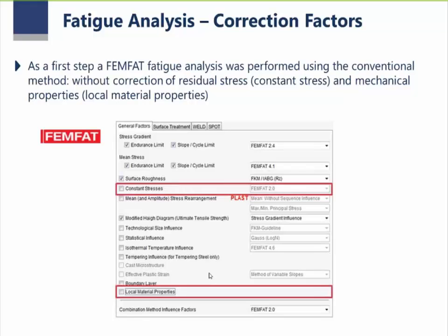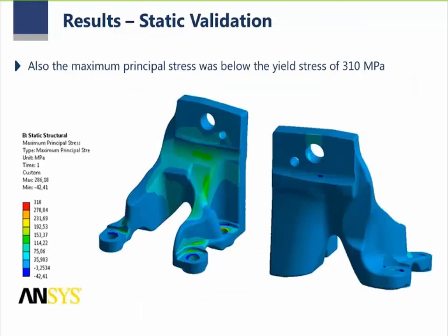In the standard procedure, when you have a simulation, you consider that every element of your model has a standard value of tensile strength, and also a standard value of the fatigue endurance. But when we get these properties from the MAGMA simulation, you see that there is some variation from part to part. So in this presentation, I will not go very deep into how to show this inside the software.